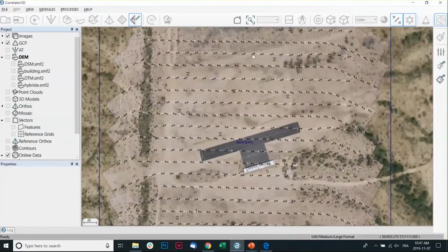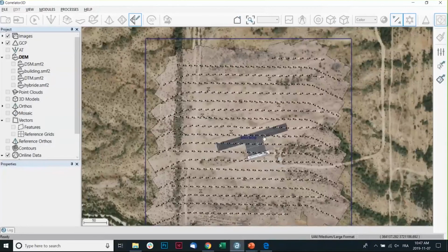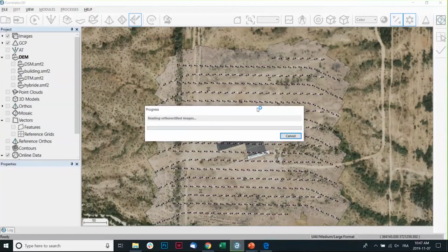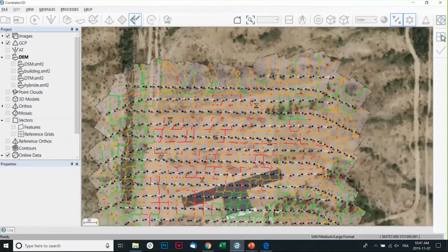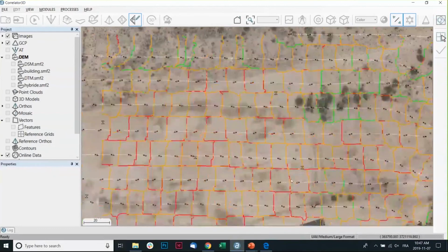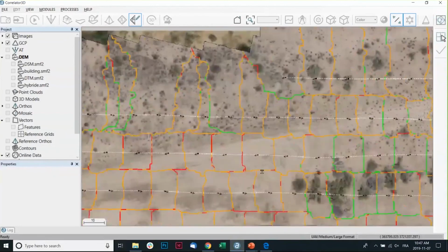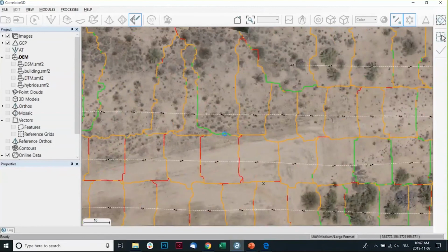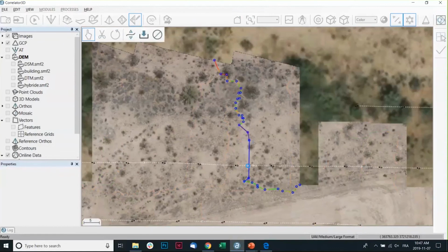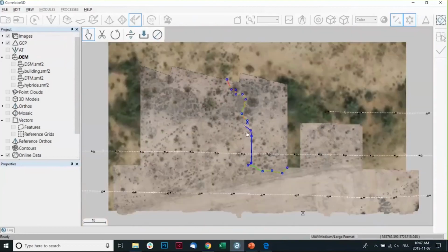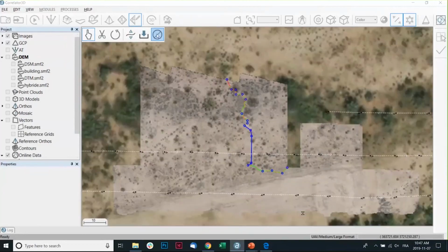It's a seamless mosaic that was generated, and by selecting your block, you'll be able to edit the seam lines of your project. The seam lines are the lines that were used between two images to generate a seamless mosaic. So I can edit one seam line like this, click on it, and only edit certain parts of the mosaic in order to have better results if I want sharper results.